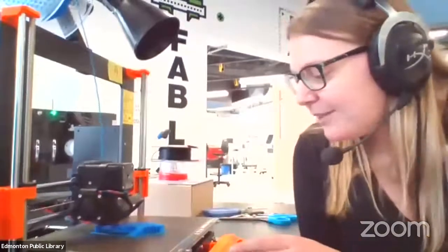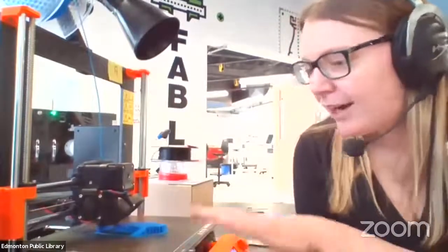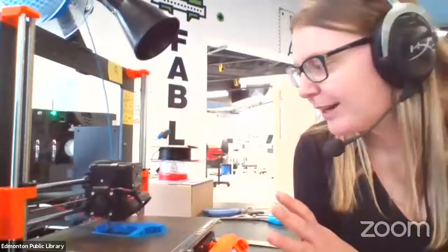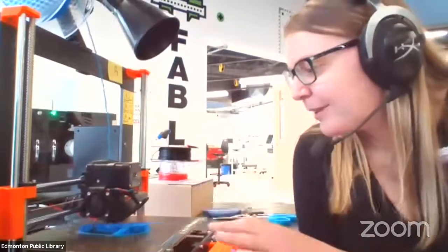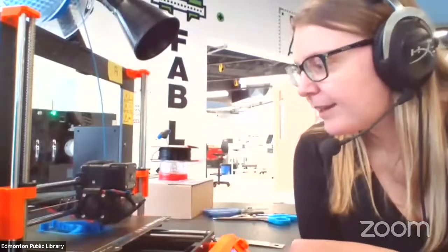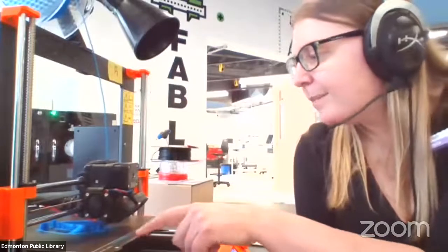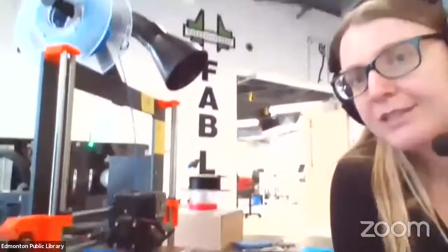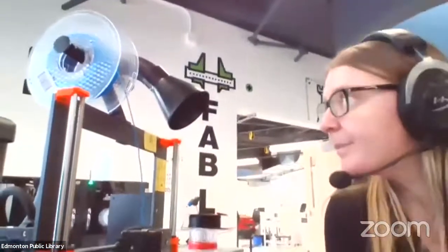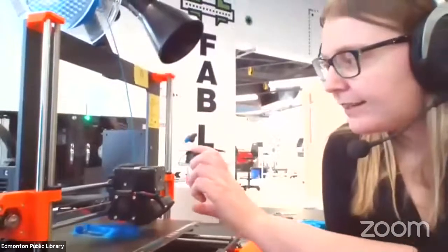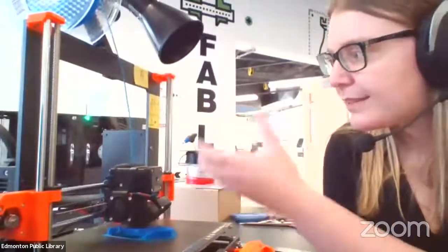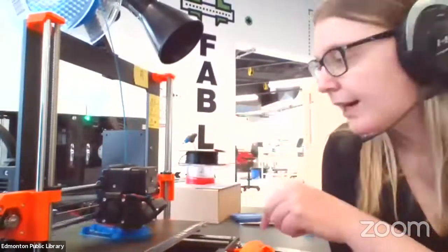So basically you can see the 3D printer. This is a hot plate here, so I'm going to be careful with my hands. But we have the 3D printer going line by line. It's got basically this blue material that's coming down from the filament at the top. And we have essentially the hot end here and what's called the extruder that takes the filament and pushes it through into the hot end.